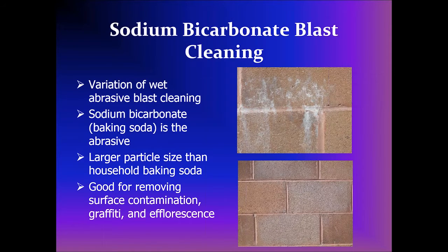Sodium bicarbonate blasting is another variation of wet blasting. In this case, you're using baking soda, which is water soluble. Now, it's a larger size than household baking soda, but does a very good job of cleaning the surface. The baking soda is added right at the nozzle, so it doesn't dissolve by the time it hits the surface. And yet, when you're done, you have no abrasive to get rid of. It's just solubilized sodium bicarbonate and water.